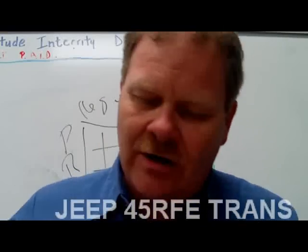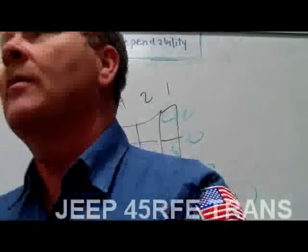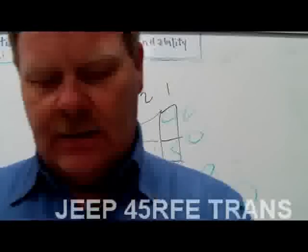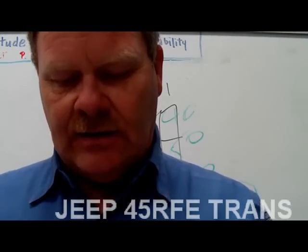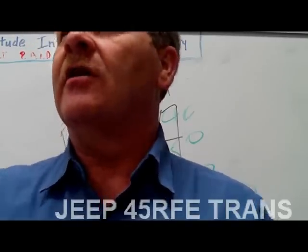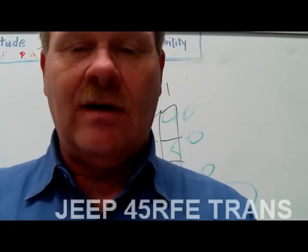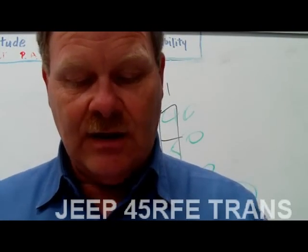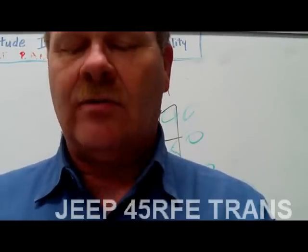In addition to the inputs wired directly to the TCM, there are other inputs it obtains from other control modules over the PCI bus. That's a kind of bus that only Chrysler used. It's like a one-wire bus. They're indirect inputs because the other modules are sending those inputs to the TCM, and it's using those to make decisions. Even though it's not hardwired, it's still getting that information. So if the bus is down for some reason, the transmission control module won't be able to receive those inputs.